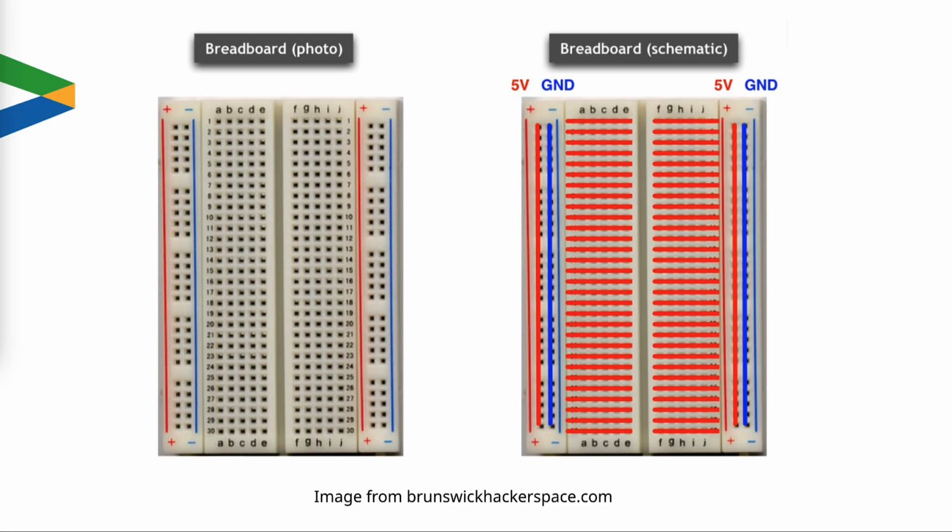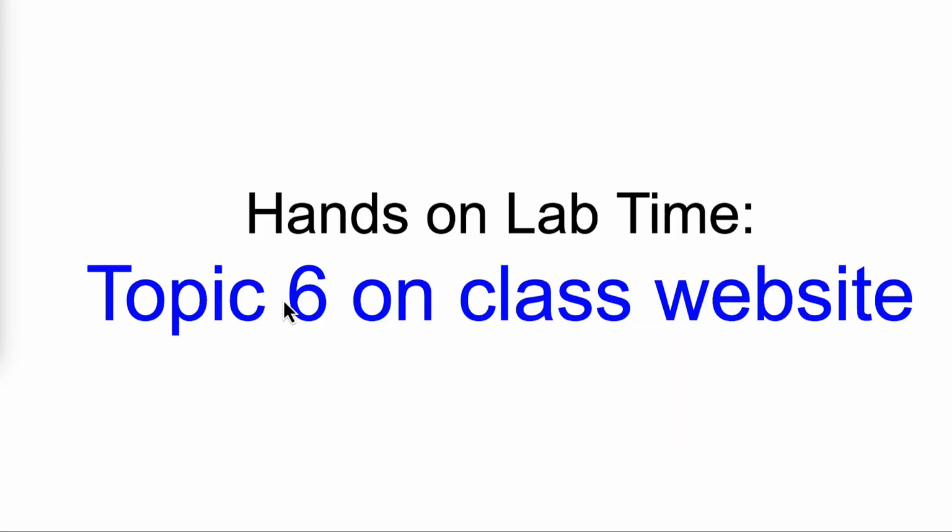Just a reminder about the breadboards that we're going to be using for prototyping. These outside rows or columns are all connected. They're separate horizontally, but connected vertically. So you've got the negative and the positive that are separate but connected this direction. Then in the middle, they're connected horizontally up until the middle. These two separate sections on the same line are disconnected by the middle bit. Just a reminder as you're plugging things in how things will route themselves.